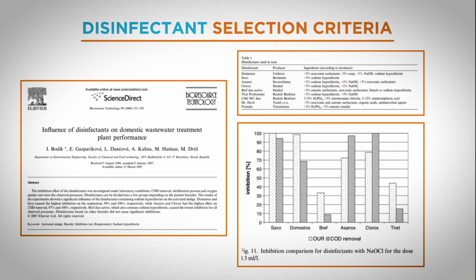Another study that looks into the effects on the microbial population responsible for wastewater treatment comes from Bodek's group in Europe. They actually looked at a system where they had reduction of chemical oxygen demand by bacteria in a controlled laboratory environment. Now, you will recall that chemical oxygen demand is one of the key parameters that the Department of Natural Resources or the local EPA looks at as far as the quality of the wastewater that we're putting out.